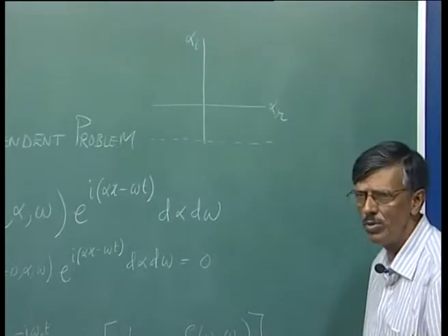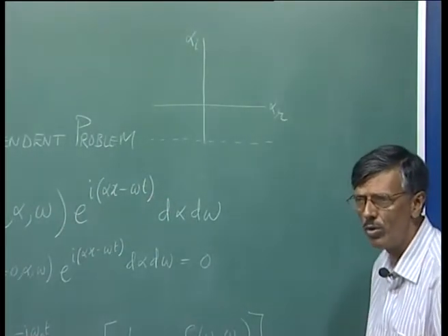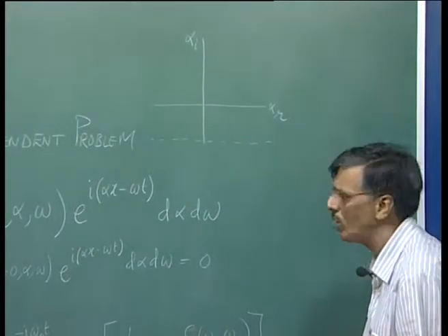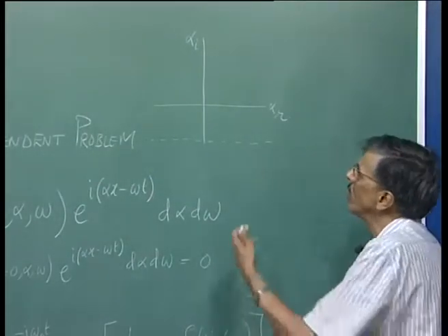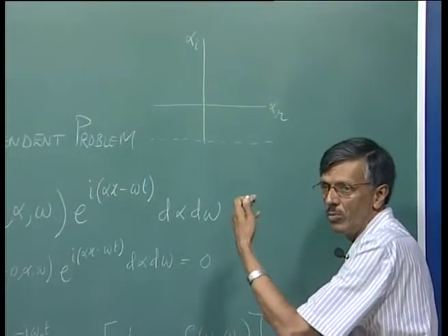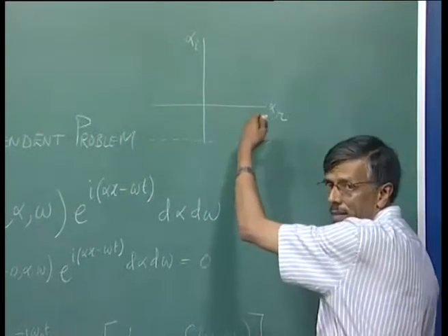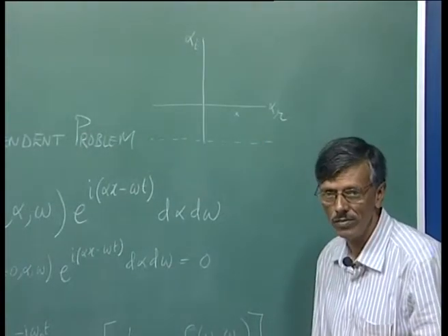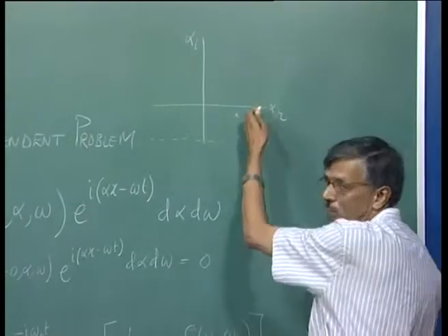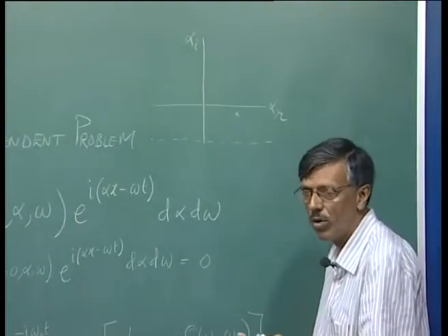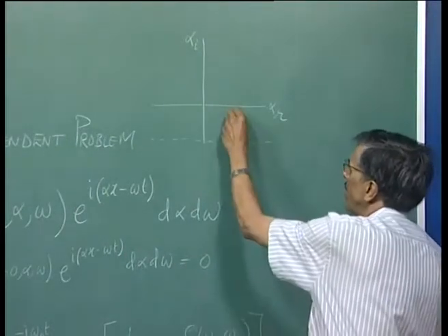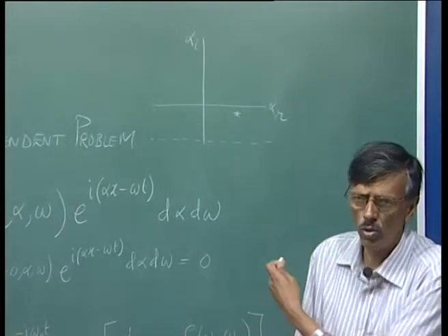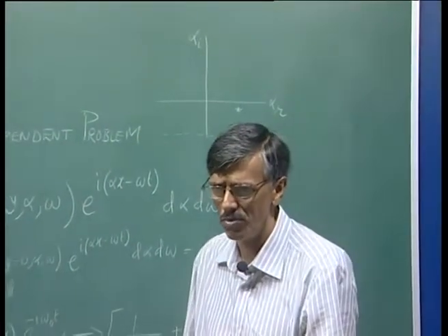Why? Because we know there are modes which go downstream and they are unstable. So, if they are unstable, that means what? And going downstream, where would those eigenvalues be in this plane? That will be somewhere in the 4th quadrant, right. Alpha is positive, alpha is negative, that is what we saw. So, these eigenvalues, if they are there, relate to your unstable TS waves.